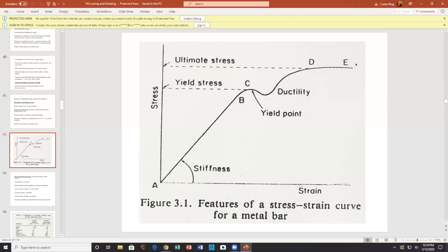It has no stiffness or very little stiffness. It can tolerate huge amounts of strain, and the stress level may be intermediate to small. And you're likely not to reach the ultimate stress. The ultimate stress up here is where this thing breaks. Here it acts as a complete solid.